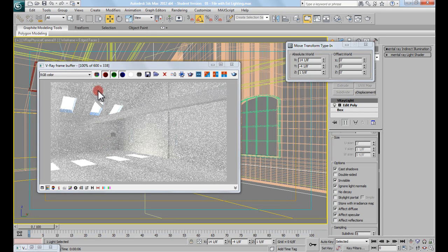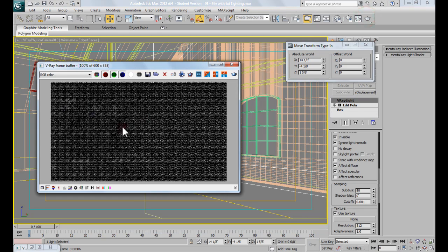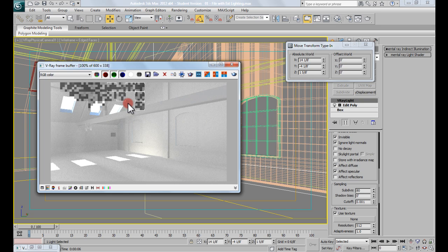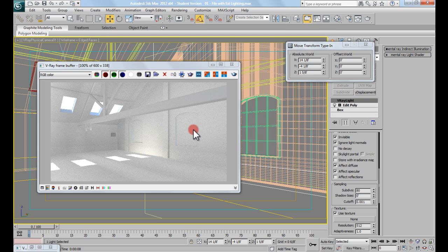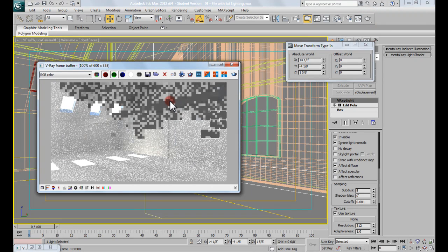So you should have something like this, and you can see it's pretty stark white now in terms of everything being balanced out. And again, don't worry about the artifacts on the screen. It's because my settings are incredibly low, just so that this thing runs super fast. If I really wanted to, I could come down to where my subdivides are here, crank them up, hit render again, and that's going to clean it up. But I have my global subdivides turned down super low so that this is going to render out fairly quick. All I'm interested in is looking at the overall lighting quality and balance within this space. So I really don't need my subdivides turned up. I can have everything super low and still get a general sense of what the lighting is doing in the space.